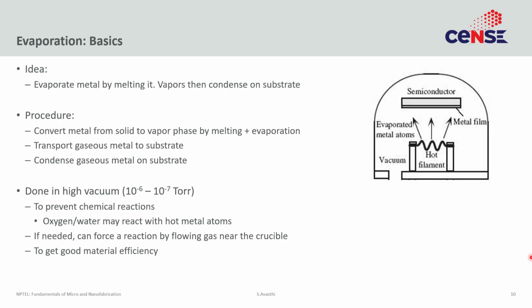So the basic idea of evaporation is about as simple as it gets. You have a vacuum chamber and a filament, and that filament heats up the material that you want to deposit to a point where either the material melts or sublimes. That creates this vapor, and these evaporated metal atoms are just transported by line of sight onto the semiconductor and they condense. This is essentially what happens if you take boiling water and put a lid on top, and if you pick the lid up after 2 minutes, you will see water sticking to the underside. This is exactly the same process.